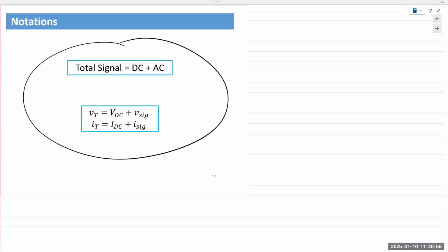So if you have an op amp and you apply a DC source of like 10 volts to it, and you apply an AC signal, your output cannot exceed the DC source. And what that op amp is doing is it's simply taking the AC, mixing it with the DC. In a way, you're giving the shape of the AC waveform to the DC. Okay, so the power comes from the DC. It does not come from thin air. So you cannot use it just for power generation. And so oftentimes we will look at circuits where you have both AC and DC signals, and you need to distinguish between the two.